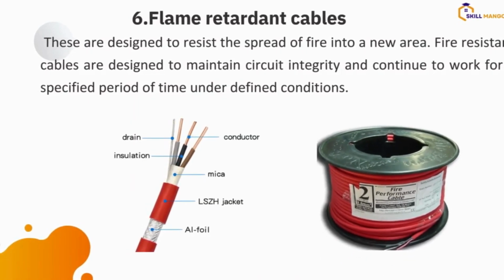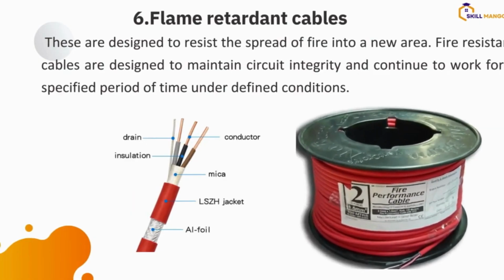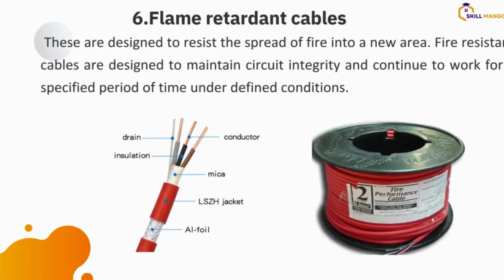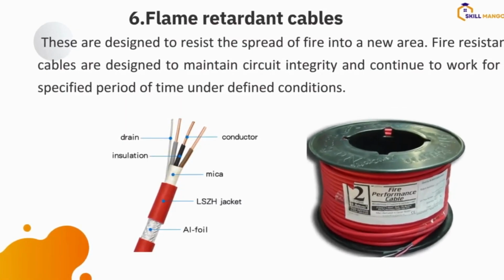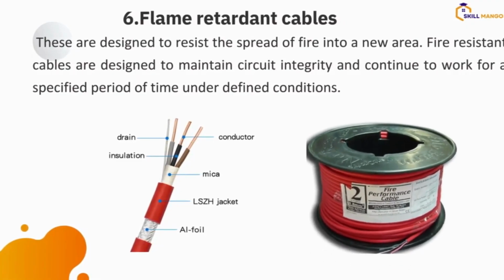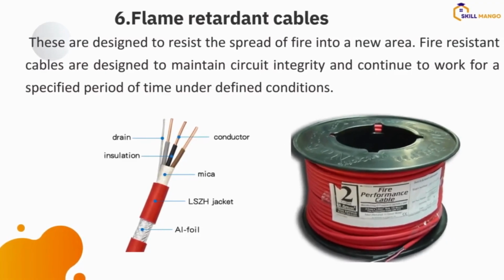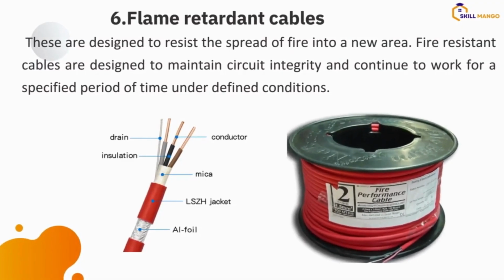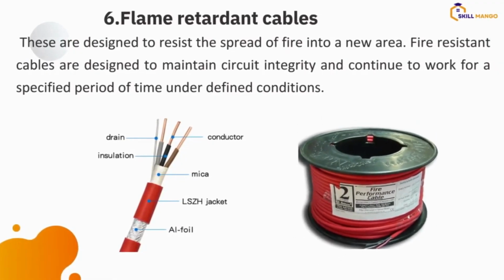But in the case your client is having difficulty getting this kind of cable, you can also use the red and black electrical cable, pure copper. You can see the copper content of this cable is pure straight copper and it's about 1.5 mm. This particular one here. All right, so you can get a similar electrical cable. It will still serve the same purpose and give you exactly what you need.